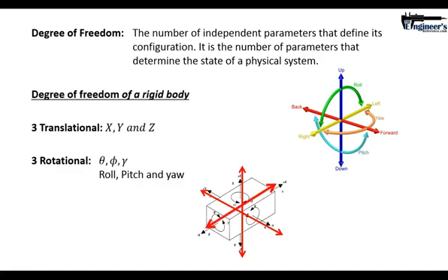Now, I want you to think of that phrase there, a rigid body. Each one of the links in that robotic gripper was a rigid body. The 2 claw ends were rigid bodies, the links that connected it were rigid bodies, and the gearing system was a rigid body. Each one of those, unconstrained, has a degree of freedom. Now, what's the key here? They weren't truly unconstrained. They had something that constrained them together, something that helped them get from just being a free-to-move physical body to being something that had a purpose behind it.